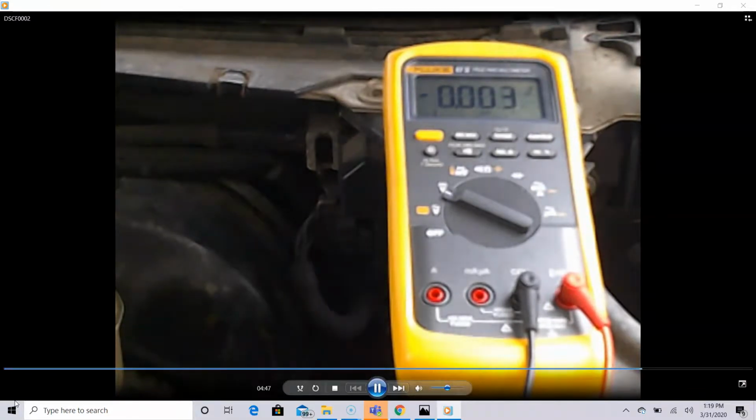Now I'll tell you about a past experience. A million years ago, I worked on a 1988 Chevrolet Celebrity, 2.8 liter. And you would take the car and you would lay into it, and it would wind up in RPMs, and all of a sudden the vehicle would start shutting stuff off and the car would die. When I checked the voltage drop on the ground side to the PCM, it totally disappeared under load. All of a sudden it went from 0 for ground to 2 volts, to 4 volts, to 6 volts, to 12 volts, and naturally no ground to the PCM. So I had to take that ground wire and supply my own ground to the PCM to fix the car.